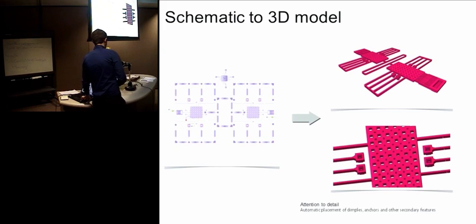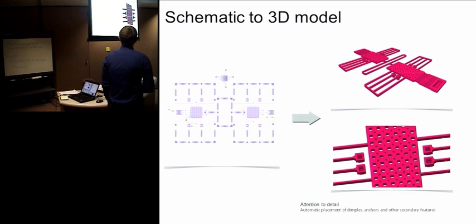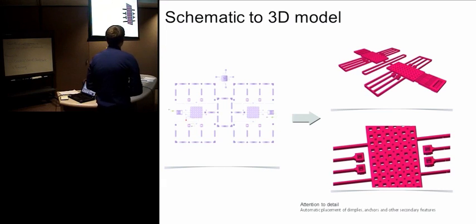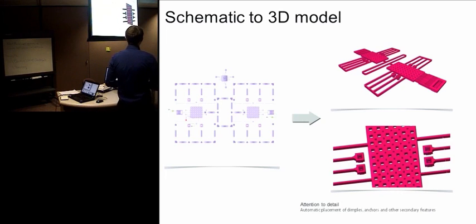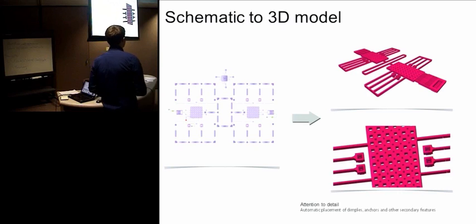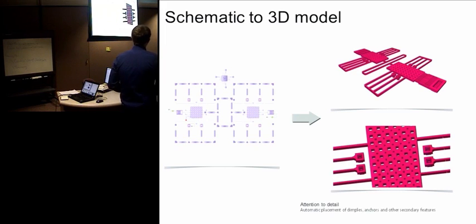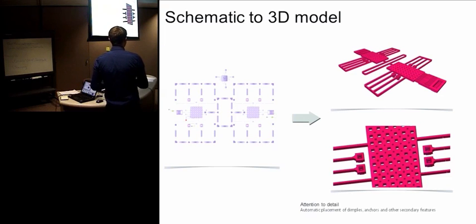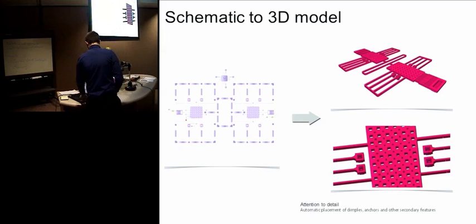And then from here, using a tool called Quick 3D, we can easily build up a 3D model. And we're able to export a couple of different file types. So we have all of our IntelliSuite file types, and then we also support IGS and a few others. I believe IGS is compatible with SolidWorks and Pro-E. So I know some of our users have been using Quick 3D, where they will just resave it as an IGS file and then bring it into SolidWorks to produce their technical drawings and everything.